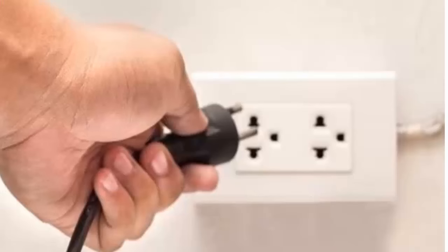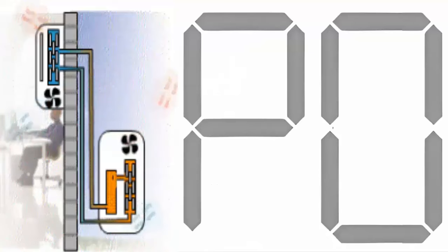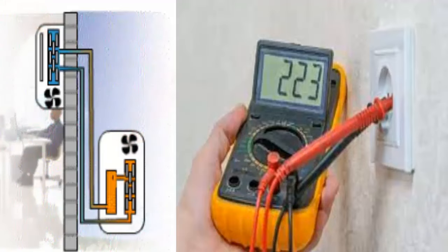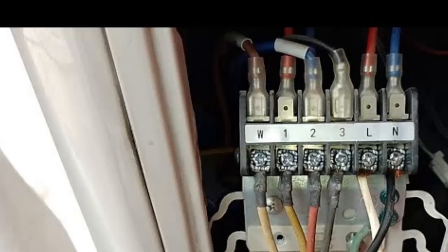1. Disconnect the equipment from the power supply for several minutes. 2. Reconnect the equipment and observe if the error disappears. 3. If the error persists, use a multimeter to check if the power voltage is normal. Also, examine the connection of all equipment cables.